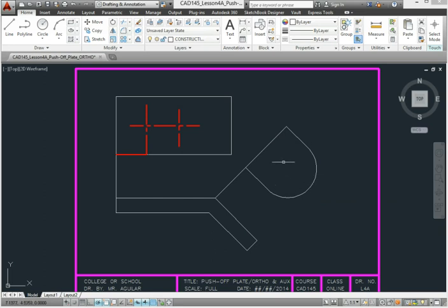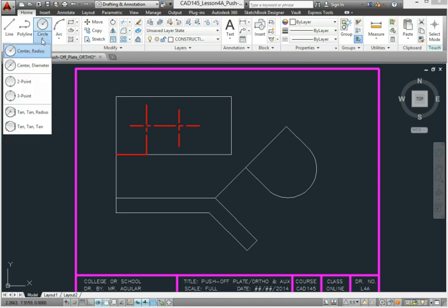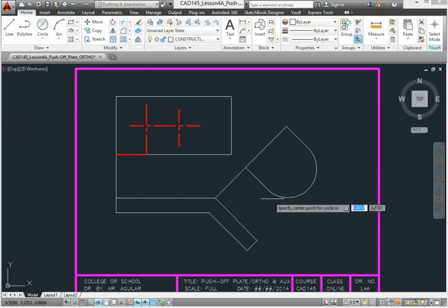With an arc, we now have a center point to draw the other hole. The hole is measured as a diameter, which means you need to switch from circle radius to circle diameter before you draw it. Hover over the edge of the line to look for the center. Snap to the center and type in a diameter of 3/4.